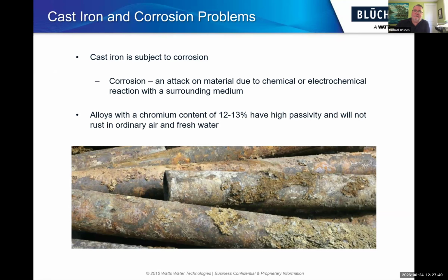And then it gets to site, waiting to be buried. It's still corroding, so it starts almost right away. It's a fairly rough surface, so if there's any bacteria in the water, it will cling to those rough surfaces and start to form what's called a biofilm to protect itself.